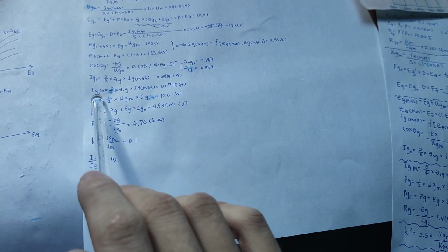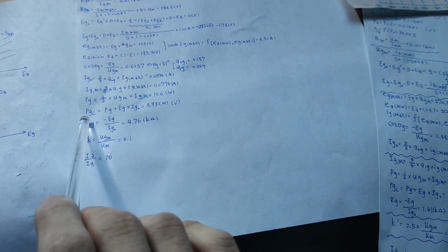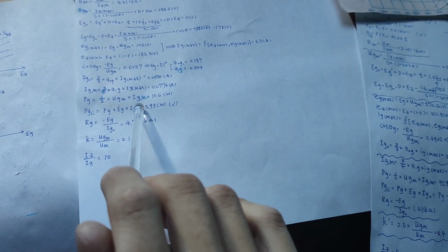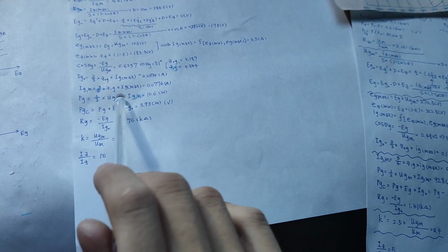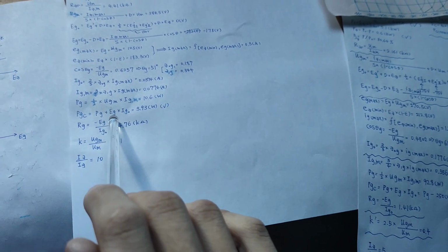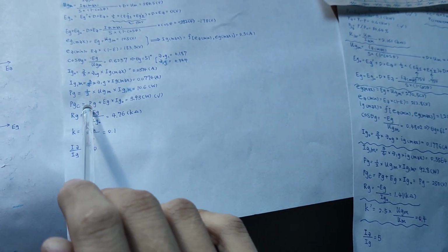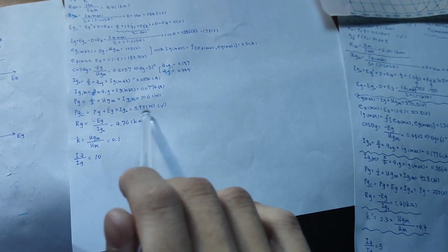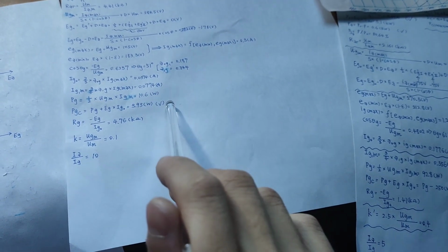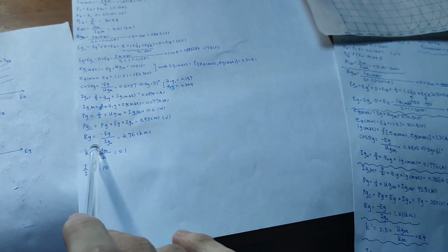and we can simply get our gate current, grid current, and grid maximum current, and the power we need to drive the grid. And this is the power loss in your tube's grid, which will minus the power loss on your grid resistor. Remember, this is a negative value, so the plus actually means to minus out the loss in your grid resistor. You can see here is just a DC power, so the total power minus this will be the power in your tube's grid, which you need to check if it is smaller than your tube's tolerance, and you can finally get your grid resistor's value.